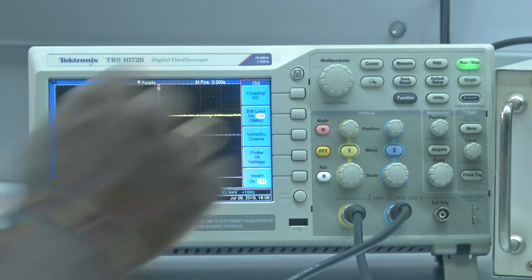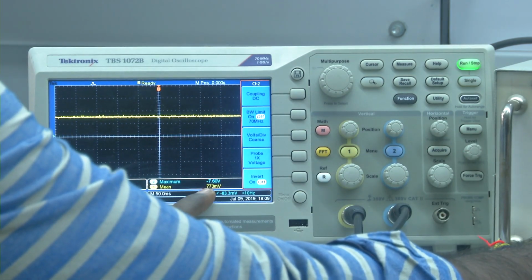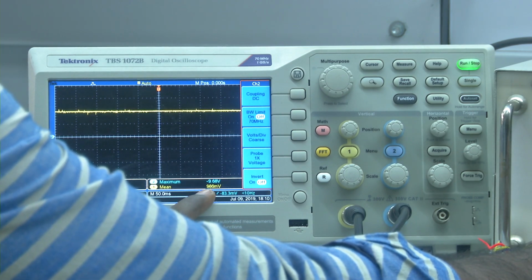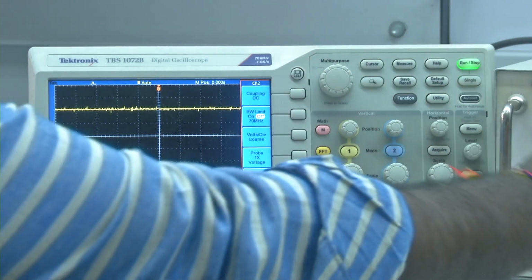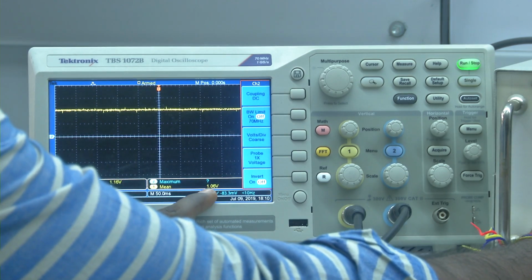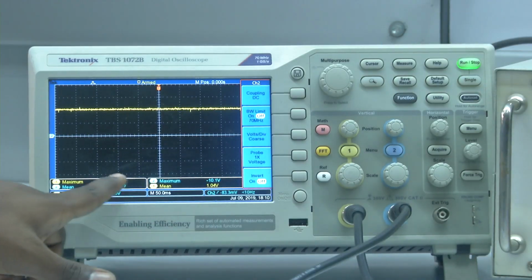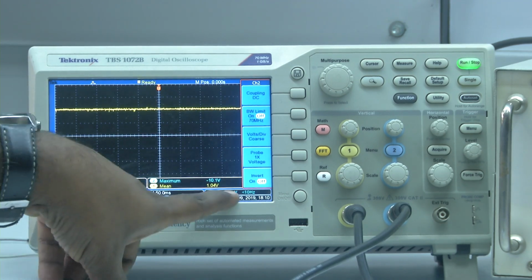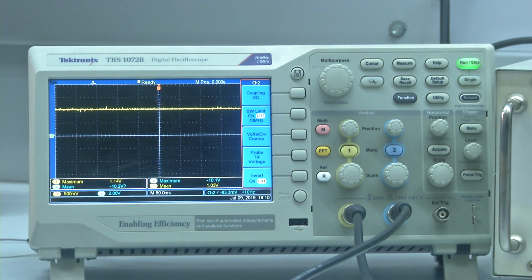So now if you observe, I am giving 1 volt. Let's see what I get when I give an input of 1 volt, right. So I have provided input of 1.04, I am getting output of 10.2. So from this we can clearly see that it has a gain which is close to 10. 10 point something, but very close to 10. The magnitudes are the same, but there is a phase.